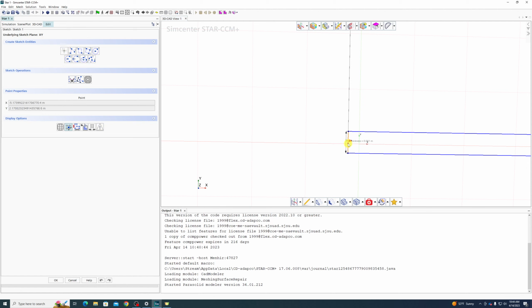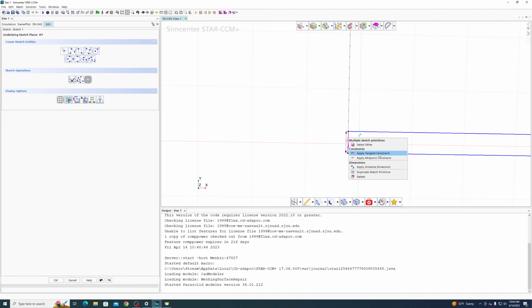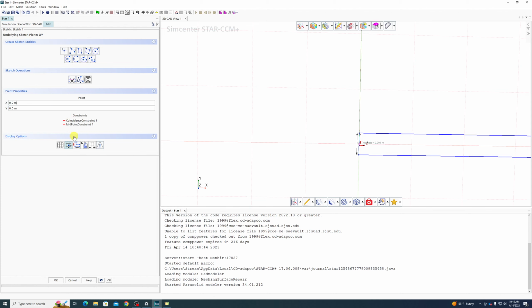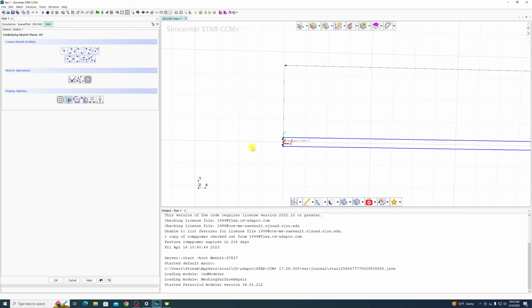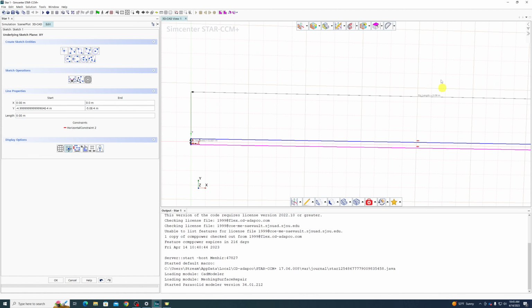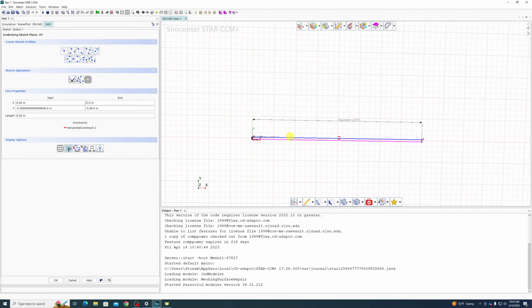So what we're going to do is put a point here, and select the point and the line and say, hey, that point, you're at the midpoint. We are going to constrain this point to 0, 0. Let's see if it does it exact. And we are going to fix this point. And this should be pretty much incapable of moving now. It looks like it's tilted a little bit because the entire screen is tilted, but this is incapable of moving.